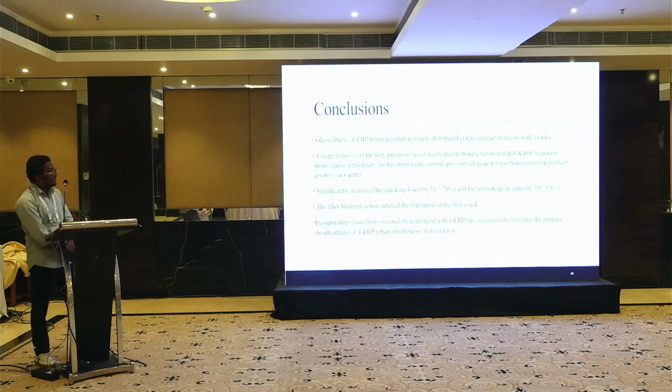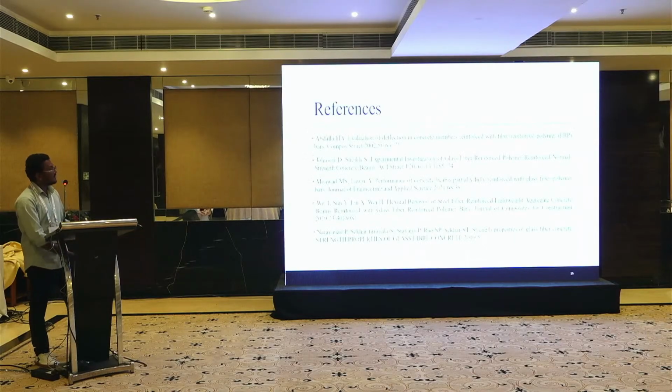Here, significantly, cracking load has increased by 54 to 70 percent, and ultimate peak load has increased up to 60%. And I can conclude that incorporation of glass fibers in concrete with GFRP successfully mitigated the primary disadvantages of GFRP, that is, brittleness and wider cracks. These are the references.